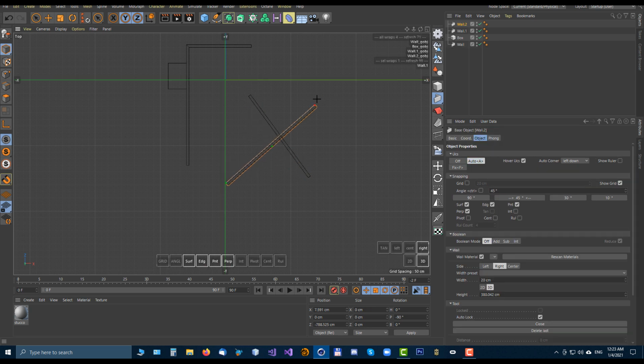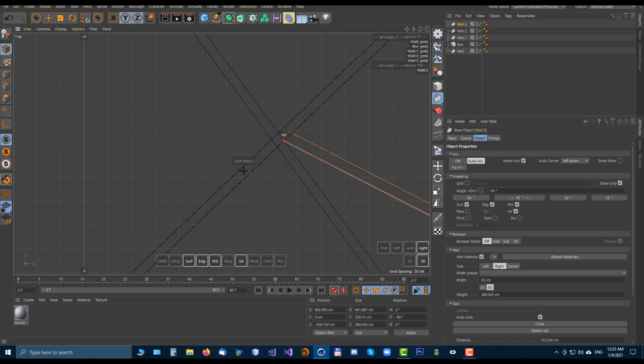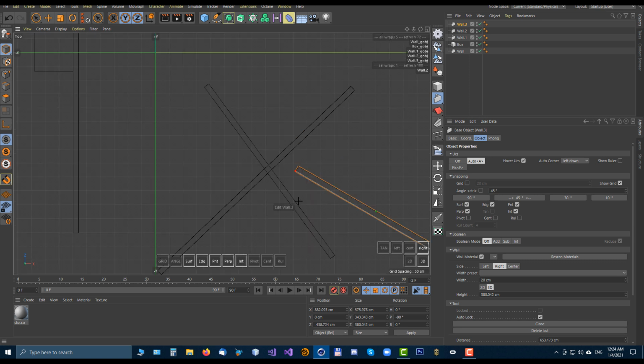Also very useful is the intersection snapping. It intersects right now only intersected polygonal edges. Also perpendicular snapping, snapping again to polygonal edges, and also roller snapping. Roller snapping now works only with edges of polygons, so you set roller division, let's say, to 10, and this polygon edge is divided into 10 pieces and you can snap on them. This is very useful.